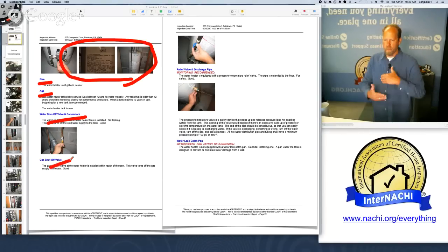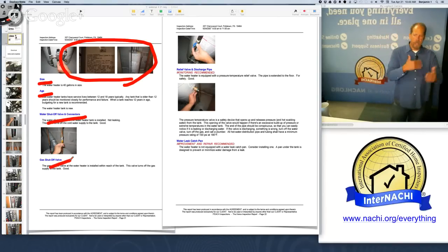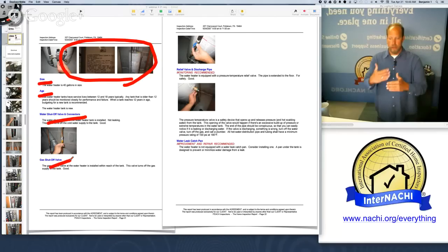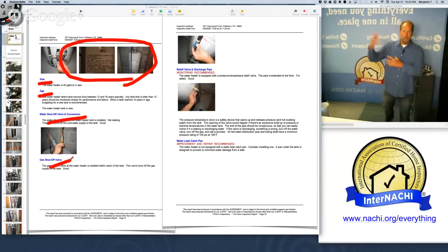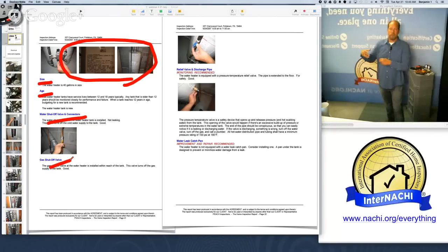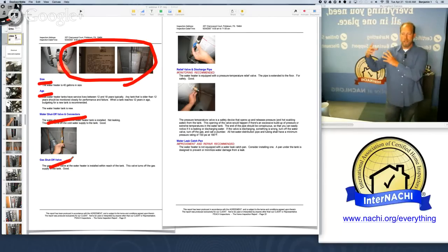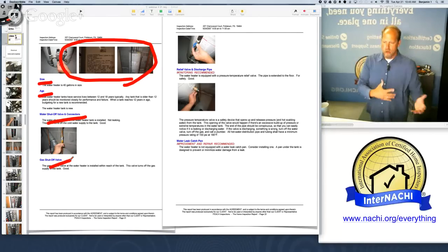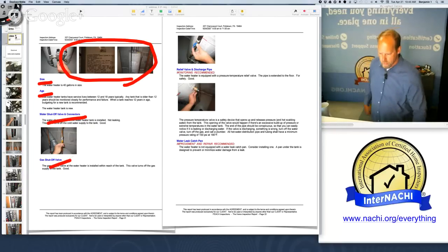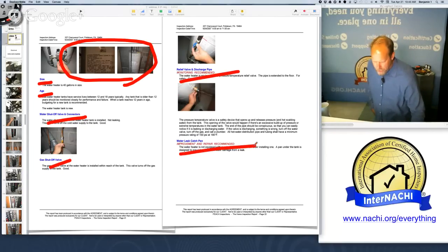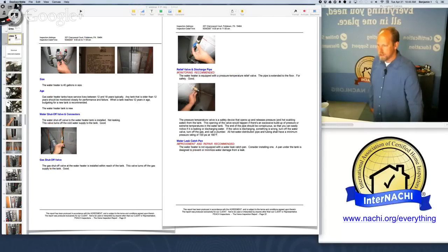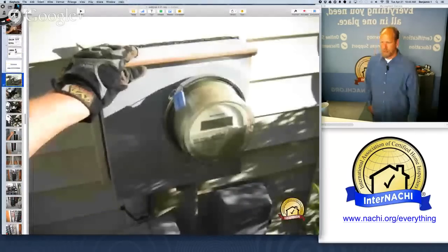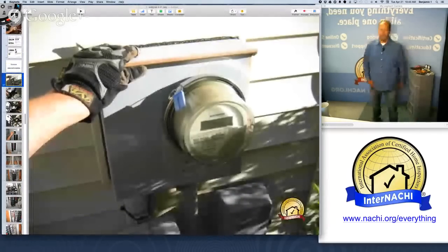And then my reports are always improving, and the way I inspect is always improving, because if I can't write it well, then I must be doing something wrong with my inspection service. So I need to tweak my inspection service and mirror my inspection service with my report. Relief discharge pipe, water catch pan is recommended. It wasn't installed. I don't care that the water source is in the basement with an unfinished floor. I want a water catch pan.